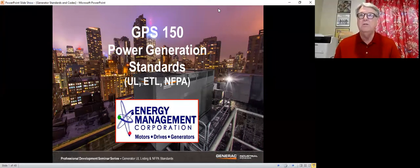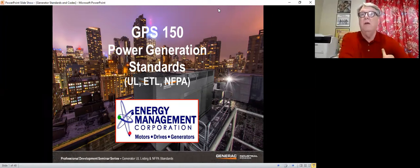Now, legally required generators could be generators that could cause health hazards. Let's say something like a sewage treatment plant. Nobody's going to instantly die, but it certainly could create a health hazard if that generator doesn't work. There are also generators that can hamper rescue or firefighting. That's NEC Section 701. Then we have optional standby generators, and that's NEC Section 702.